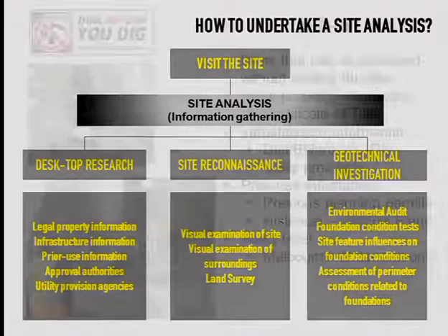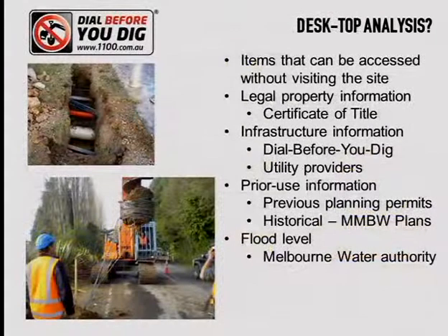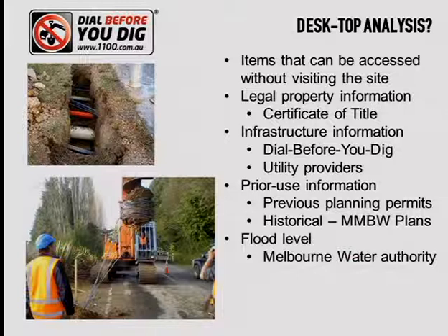So let's look at some examples of that in this desktop analysis. Now, locally we have quite a good service that will more or less tell you where most of the main services that are adjacent to a site are located. And they brought that under the umbrella of one referencing authority, which they call Dial Before You Dig. Okay? And it was really directed towards the contracting industry, to avoid this sort of stuff.